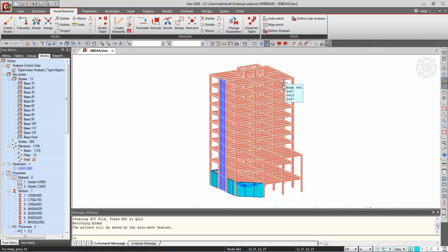No, for the core you cannot design by using the MIDAS software. You have to use Design Plus. Here you can design only the rectangular wall. For the rectangular wall, you can give one label. If you give one core as one label, it gives one set of stresses. According to that, you can take the forces and design manually. And if you want the program to design, each and every wall you have to give a different wall ID.